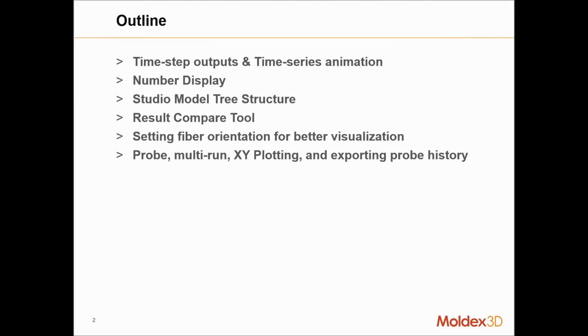How we can set up the graphics for better visualization of fiber orientation, makes it a cleaner image. And last but not least, we'll touch up on the probes, how to graph multiple runs, compare different information from different iterations, how we can use that information to plot XY curves, and how we can export them to a CSV file.